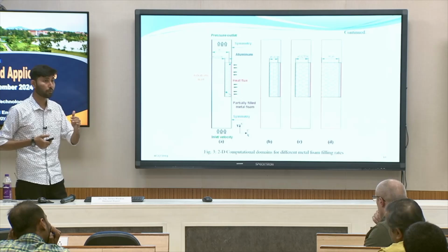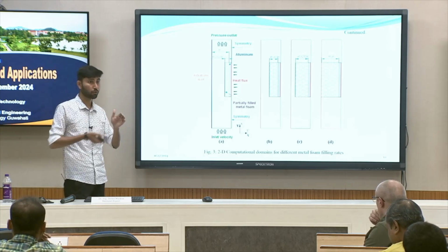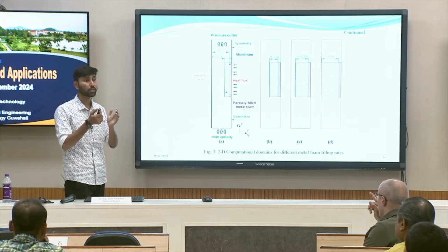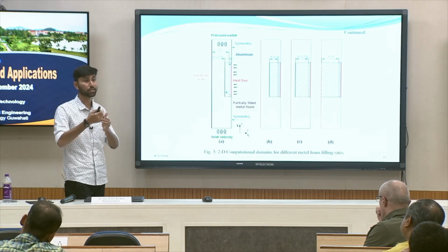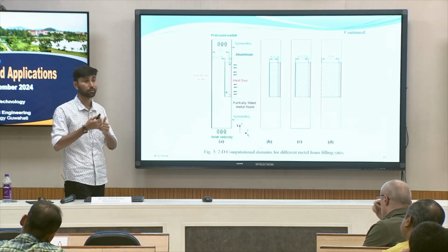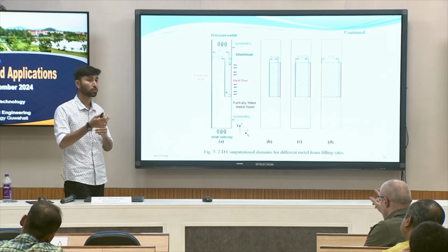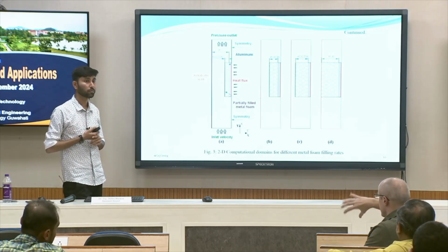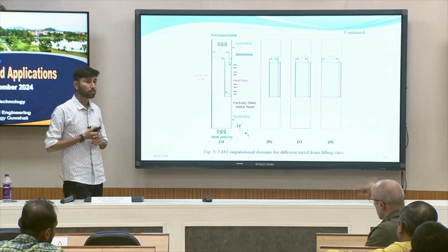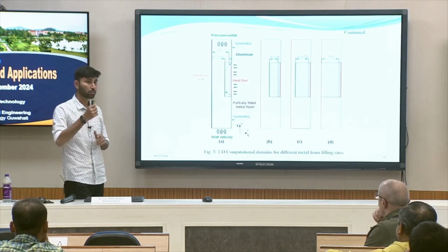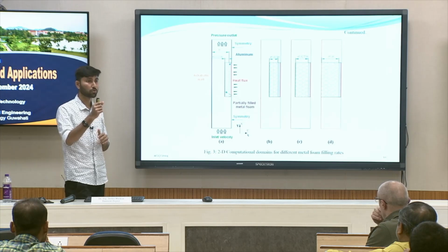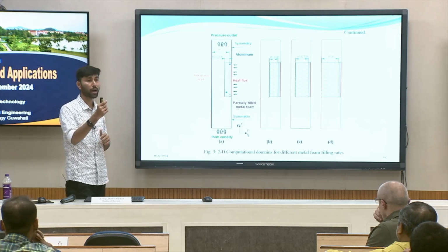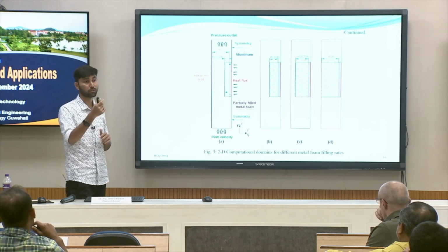Flow through the porous structure is also a very important parameter, so we have considered laminar, transition and turbulent regions. Do you resolve this with a very fine mesh inside your grid which represents the material? Yes sir, we have considered that factor also. Based on the pore diameter, we have calculated the Reynolds number.